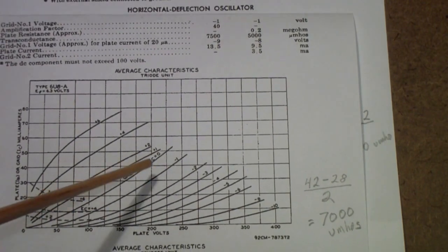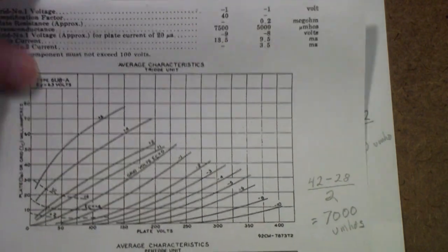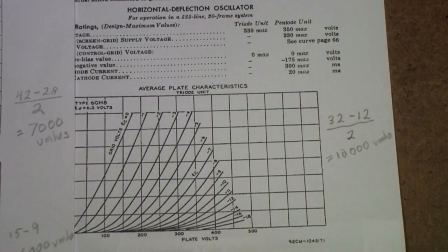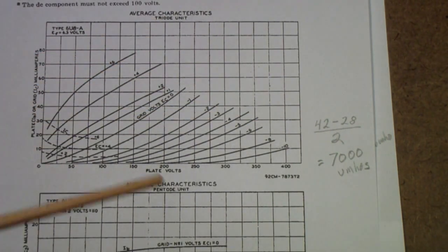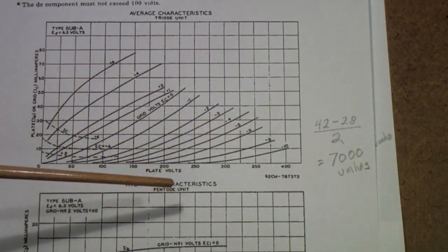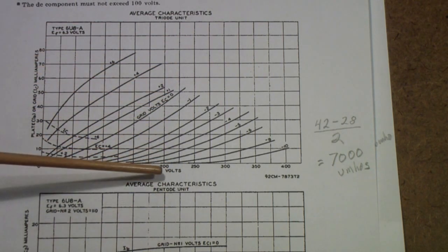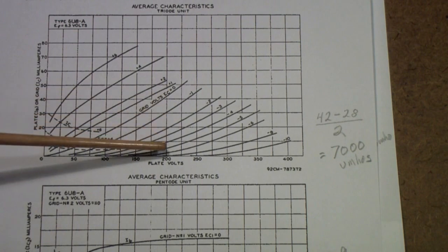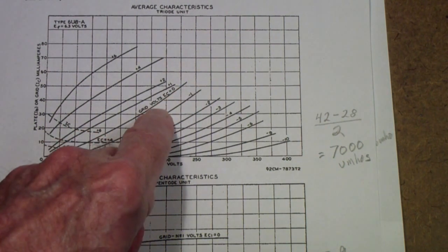Also, what you find is that the slope of these lines and the spacing between them is different. Now, I'm not going to compare them point for point. What I am going to do is calculate the transconductance, first of the 6U8. And you notice over here, I picked 2 points on the curve that were along a given plate line. That is, I think I used 200 volts. And I chose 2 points that were 2 volts apart. This is the -2 volt grid line. This is the 0 grid line.